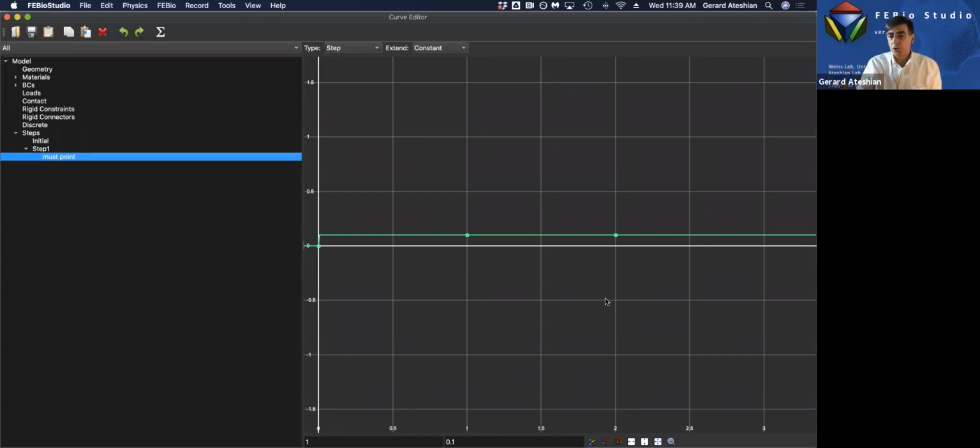So a good rule of thumb that I have found for biphasic materials, when you're doing an analysis like this, so you don't have dynamic loading that's continuously loading. If you had dynamic loading with a cyclical loading curve, then your time increments should not change too much over time. But this is specifically stress relaxation. So I'm going to have the time increments increase in a logarithmic way. It's the choice that I make.